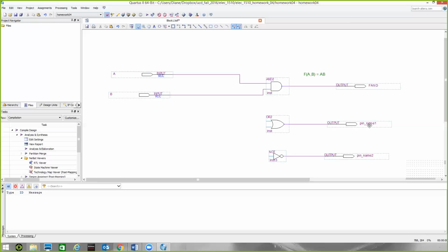All right, so we then said the output of our OR gate needs to be named GOR. Before, we clicked on our text tool and were able to double click and change names. Well, you can actually double click here as well and highlight it without going to the text tool. And so that one we're going to name GOR. I hit the enter key, and this one we name H0. We go down here. All right, so now we've got all of our outputs named to match our circuit.